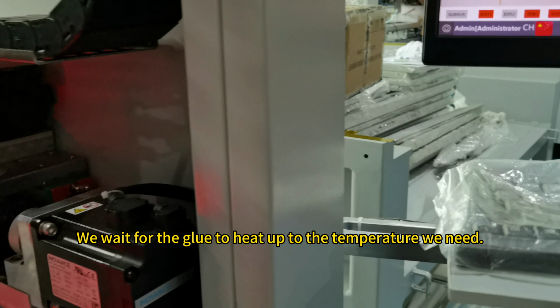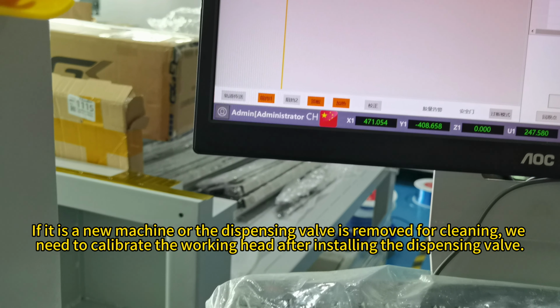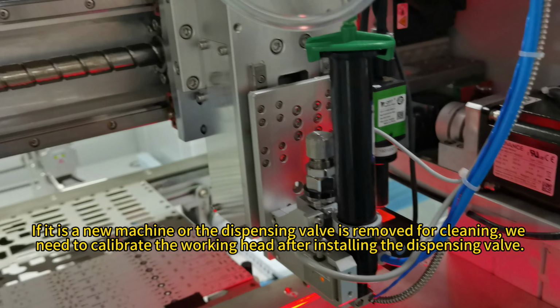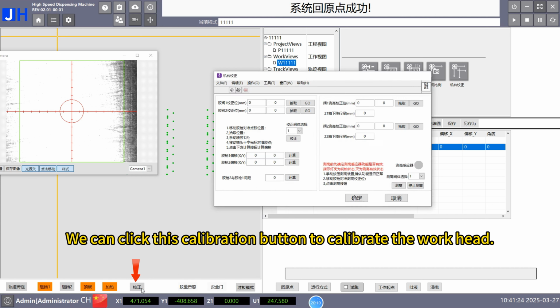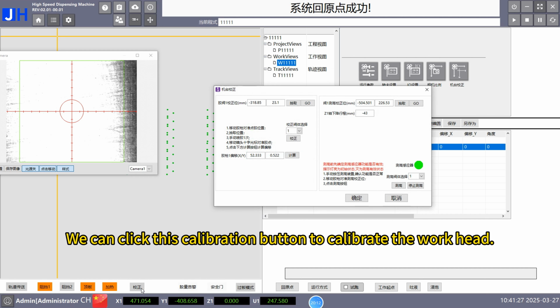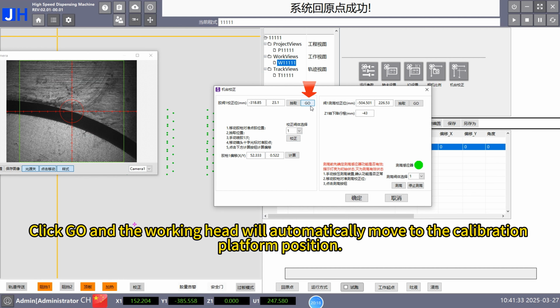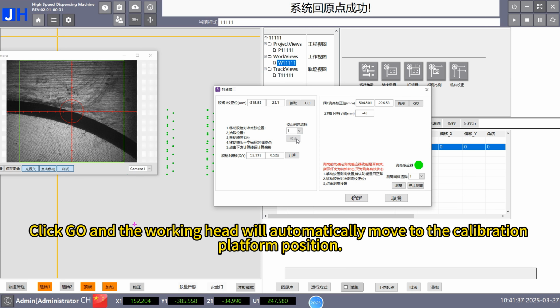We wait for the glue to heat up to the temperature we need. If it is a new machine or the dispensing valve is removed for cleaning, we need to calibrate the working head after installing the dispensing valve. We can click this calibration button to calibrate the workhead. This calibration is to calibrate the position of the dispensing valve and the camera. Click Go and the working head will automatically move to the calibration platform position.